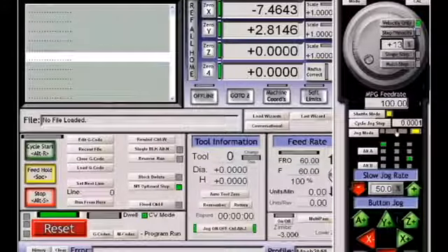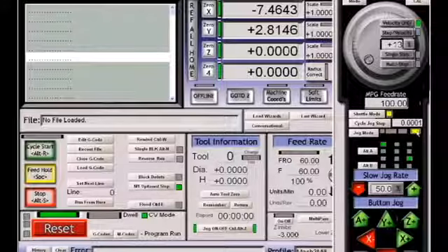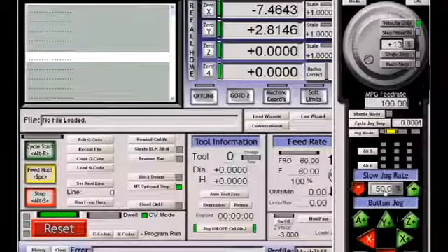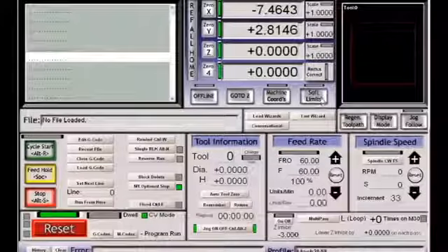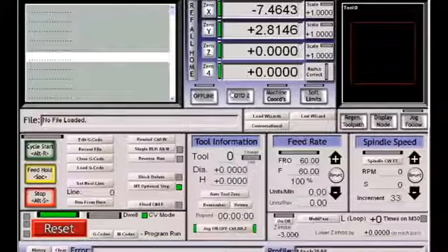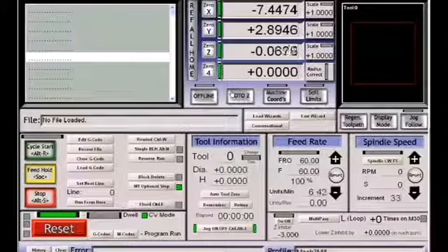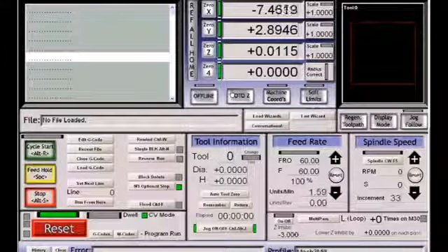The program actually runs at the speed that you rotate your MPG. You'll notice when I selected shuttle mode, our jog mode went over to MPG mode. Turning off jog mode, and we'll go back to the normal jog. So if you look at this screen, the second LED here should be lit, indicating that you're in normal keyboard jog mode, and you should have a jog speed above 5%, and you should see movement. Hitting the tab key will make that jog screen leave the screen. So at this point in the program, I can now jog, my motors are moving, and if you've tuned them properly, you should now have some pretty good movement with them.